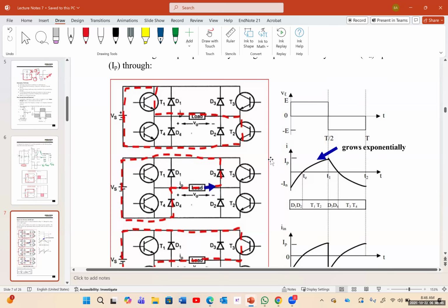And again, as you know, in DC, we won't have any problems with the inductor or capacitor. But when you're creating an AC system and you add an inductor or a capacitor, you are affecting the power factor as well. You're making it a leading or a lagging power factor, and you're changing Q. And as you know, the inductor creates a delay in the current. So the voltage changes. If we had a resistor, we would have no problem. But since